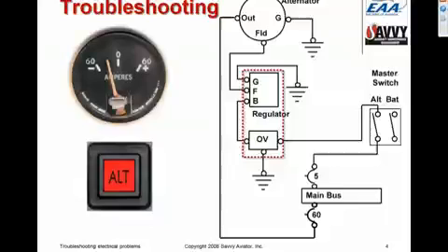troubleshooting this problem? I can tell you that in my experience, unfortunately, most mechanics aren't terribly good about troubleshooting these things, and they tend to respond to problems like this by replacing things. And there have been an awful lot of alternators replaced and regulators replaced when it turned out that the problem really wasn't the alternator or the regulator at all, but was simply a bad connection or a broken wire or something like that, which is the problem a good deal of the time.